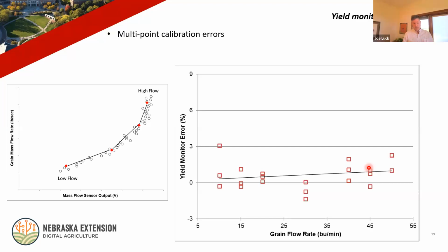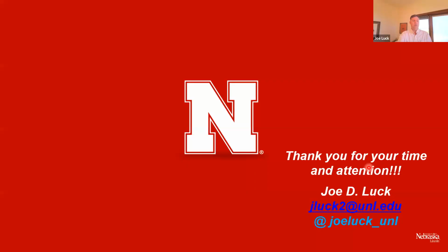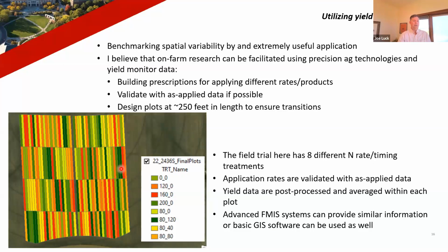We've heard that. I've experienced it personally, and colleagues that have worked with those systems say it's really good if you're just trying to get a quality yield map. When you start to get into the research plots like we showed you before, where you're going to expect pretty wide swings, they've actually found that disabling active yield and getting some manual calibrations has given them better data in these types of environments. But from a production standpoint, I think active yield has been a great thing for improving overall yield map quality. So nice.